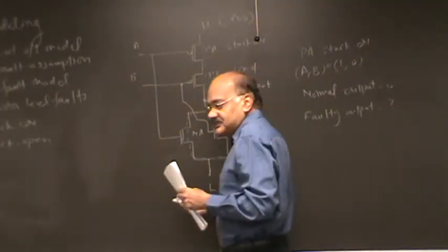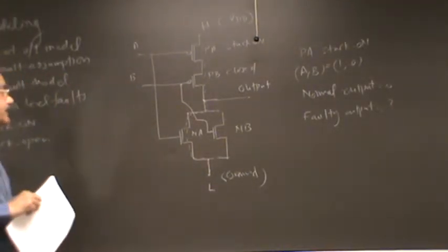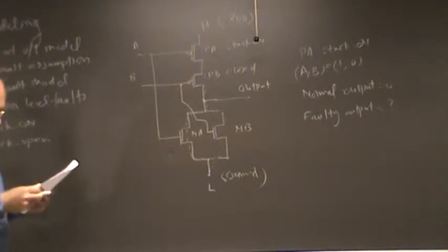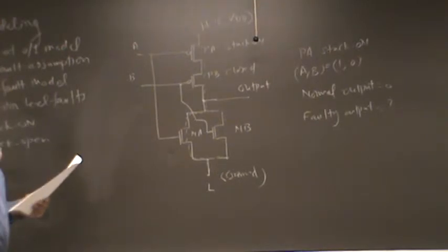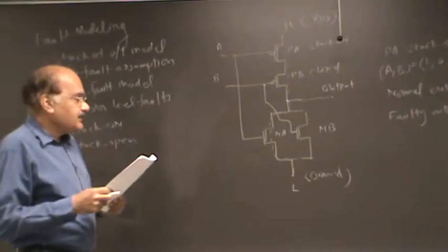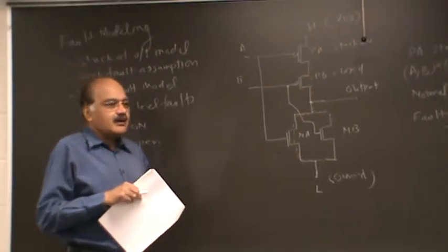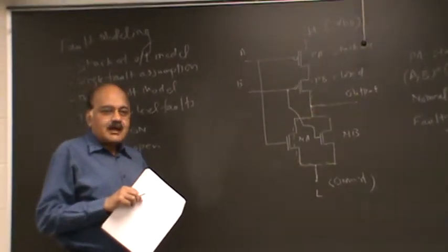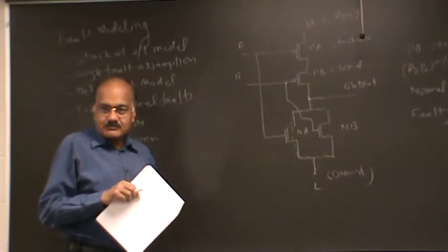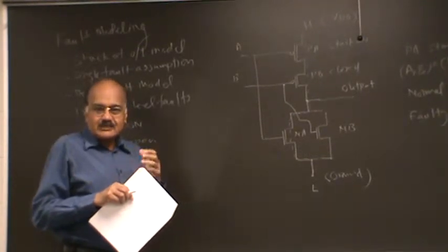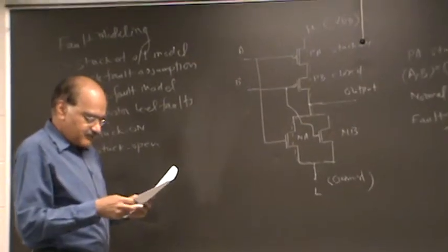So basically, you have a voltage divider arrangement, and there are two low resistance paths between high and low, VDD and ground, and it would depend on the relative resistivity, which, as I was mentioning last time, would depend on dimensions. Now, when they build these things, they use some approaches for optimizing a few things that require them to specify the dimensions. But in general, unless you are the designer, you would not know the dimensions. So you would not know the right answer.